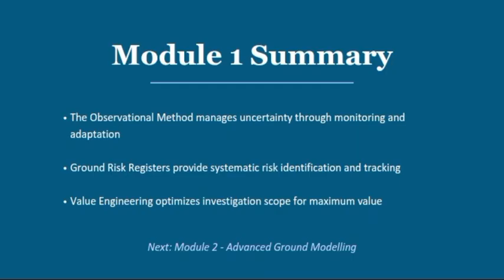Good. So let me give you a recap and key takeaways from this particular module. In summary, this module introduces the philosophy and principles of risk-based site investigation. We learned that traditional approaches often focus on excessive data collection, and that risk-based approaches prioritize critical uncertainties and hazards. We also studied the observational method, which relies on prediction, monitoring, feedback, and adaptation.